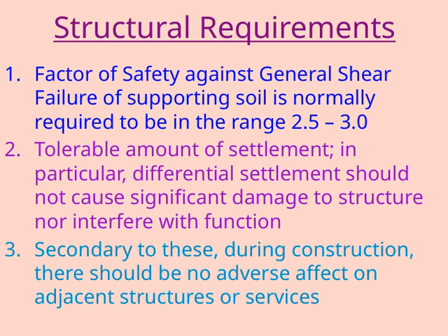It's important that the amount of settlement is tolerable, that is, minimal enough so that it doesn't cause structural damage or interfere with the building's function. Differential settlement, where different parts settle unevenly, should be kept under control to prevent cracks or structural issues.